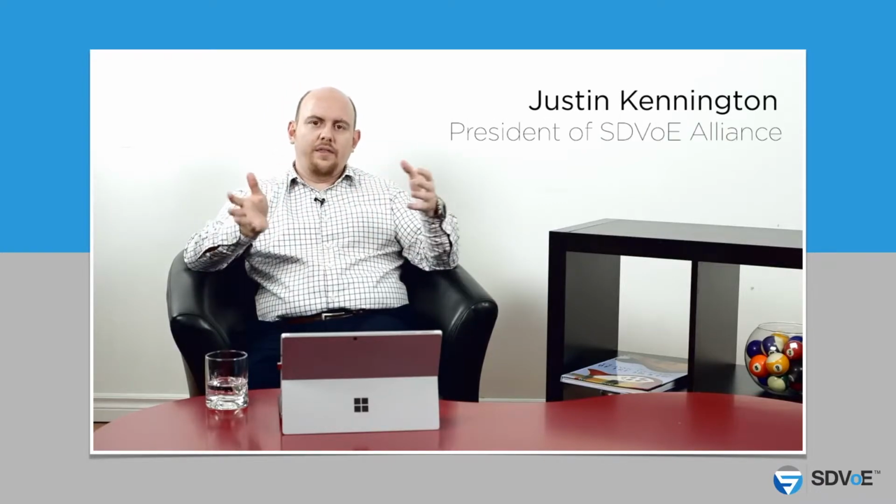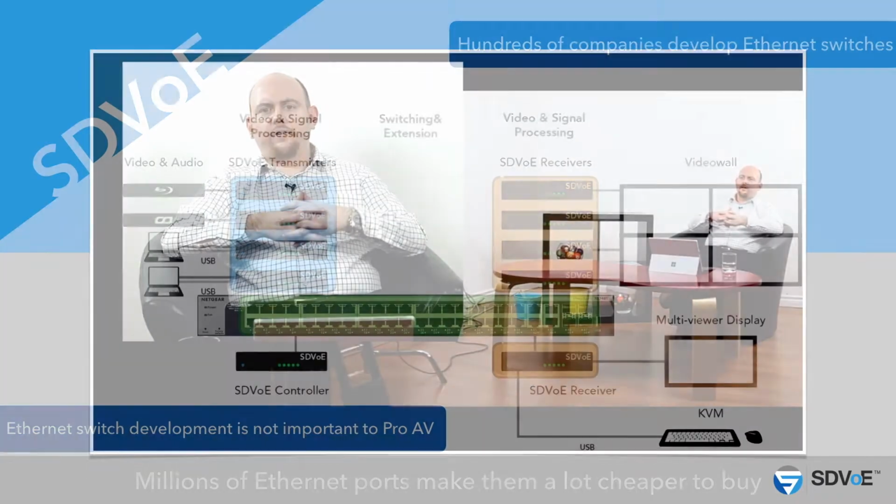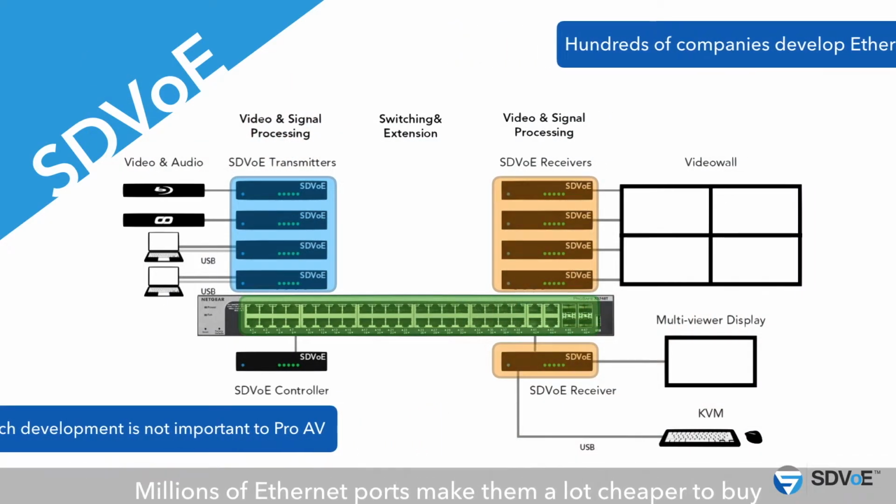However, Aptovision have developed a new technology called adaptive clock resynchronization that allows a synchronous audio-video signal to pass through an Ethernet network and then become reconstructed on the other side with exactly the timing that came in. We're actually reconstructing the clock that came from the data source, the video source, on the far end. Now, this is the breakthrough that makes it possible to say that we can replace the matrix switch with Ethernet networks. Now let's turn our attention to the endpoints.